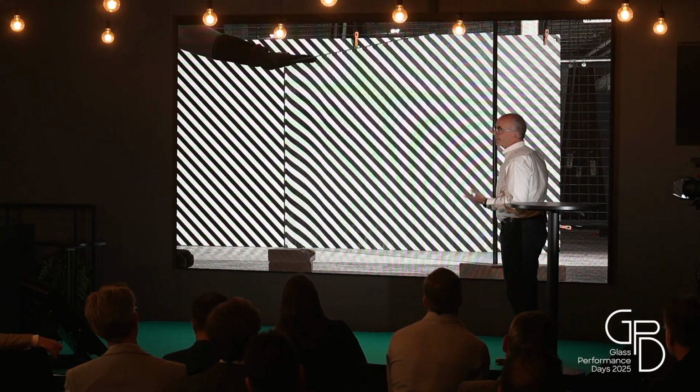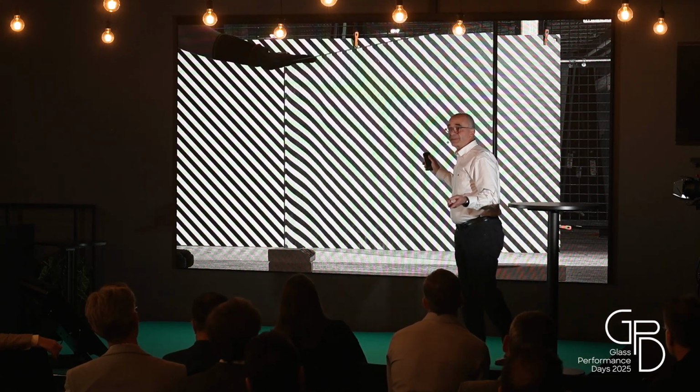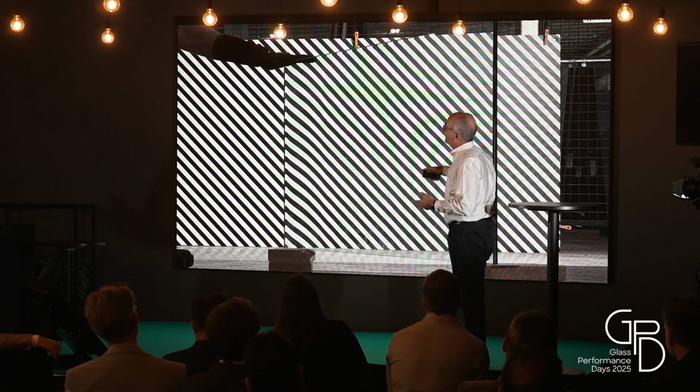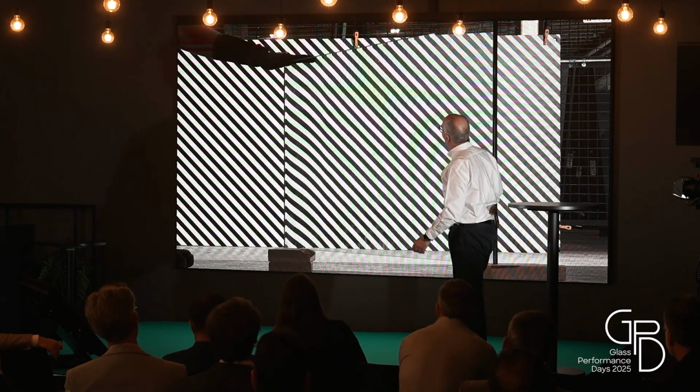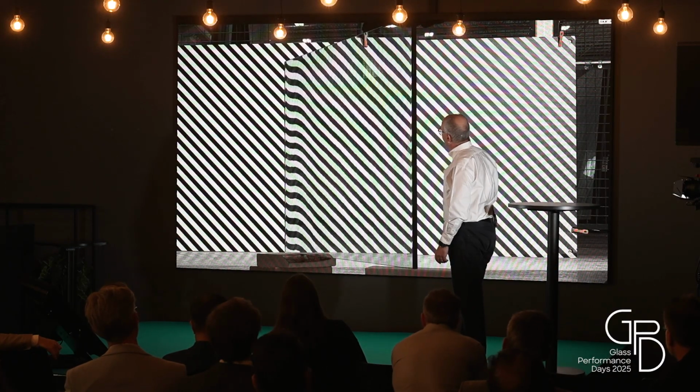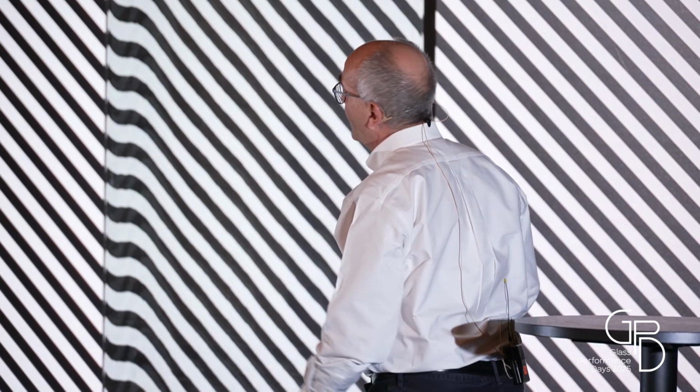So we did it with the zebra. Here I'm at 60 degrees, which is already there. It's pretty good. The laminate is inverted, so now it's on the left. That's 60 degrees, and that's 70 degrees. So you see there's definitely a distortion band there, the same one that was measured with Inspector G.